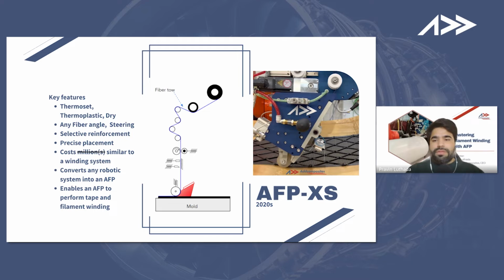Now the AFP systems that you find, like the one that we provide, are very compact and can be mounted onto existing robots. The number of robots has also exploded. Since 2000, almost for every one person you can find an industrial robot out there. Because of such a high number of robots, a compact AFP that is able to do not only thermoset but thermoplastic and dry fiber placement greatly enhanced the total number of AFP systems.